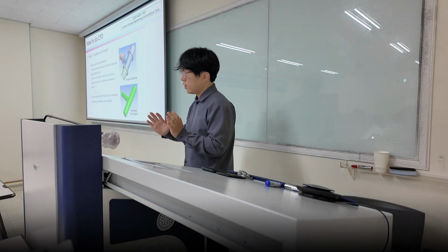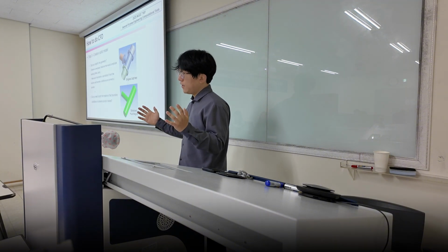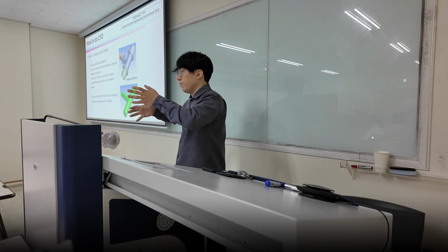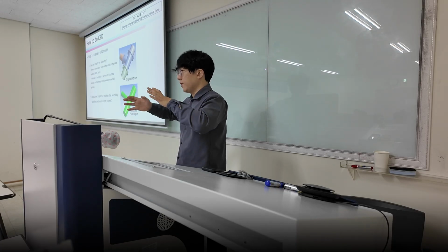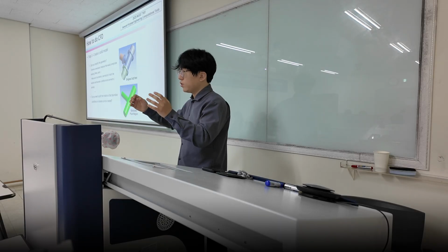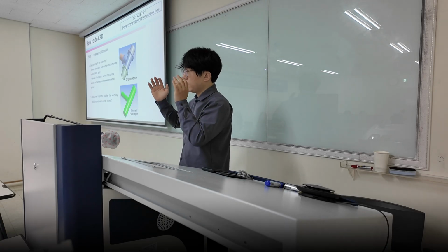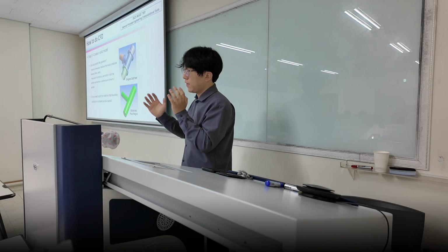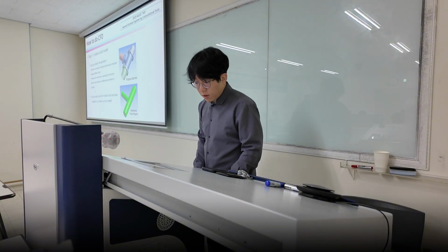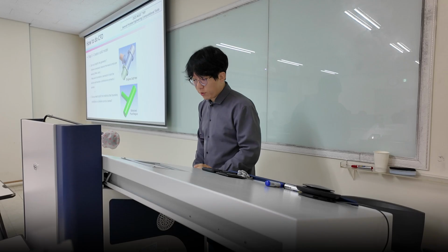If you have a big CAD part and you want to analyze it part by part, then you're going to get rid of the edges, and if it's not really significant, because small edges require higher resolution, you can get rid of them and have some reasonable amount of mesh, thereby saving computational time. So this is also really, really important.